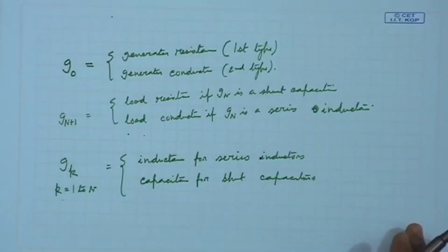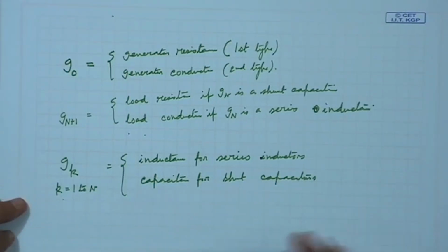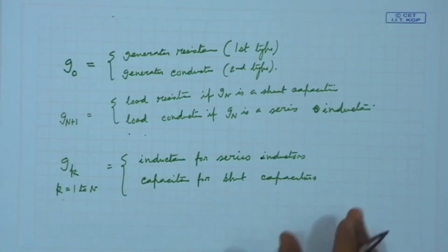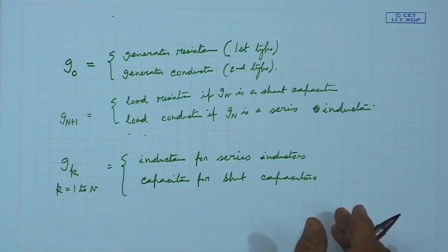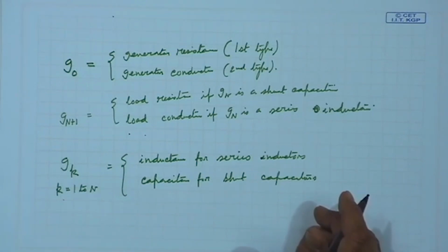It is alternate. So, suppose you can have a design where a maximally flat low pass filter is to be designed with a cutoff frequency of 8 gigahertz and a minimum attenuation of 20 dB at 11 gigahertz. That means he is specifying what your pass band is, and how much in the stop band, and how many elements are required. So, you can go and do that. We will have a tutorial, we will see this problem. Similarly, you can have Chebyshev filter design, prototype filter.